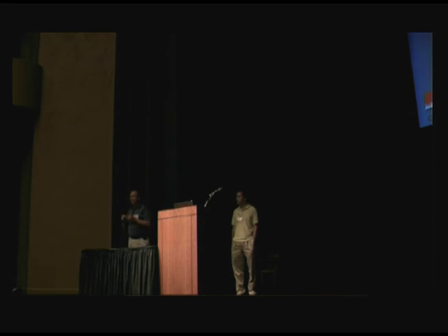Yes, we are actually. I didn't, again, due to shortness of time here. In Power 7, we went to version 2.06 of the Power architecture, which basically what we did is we merged the vector instructions and the floating point instructions in a backward compatible way. You could do a whole talk on that. The idea being that you have one set of 64 128-bit registers, then we map the traditional scalar registers and the old VSX registers on that. I believe that should be publicly available, that version 2.06 is, again, a whole section on it.